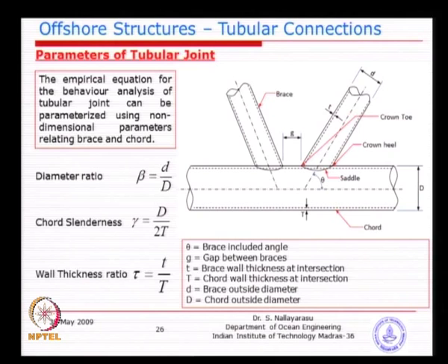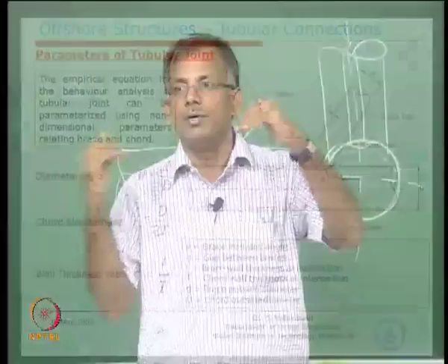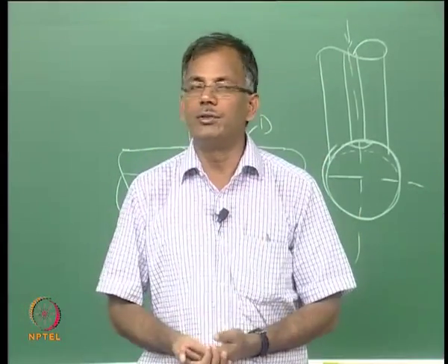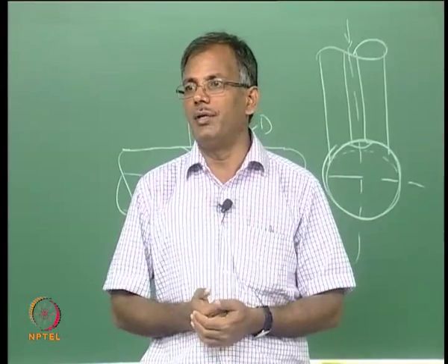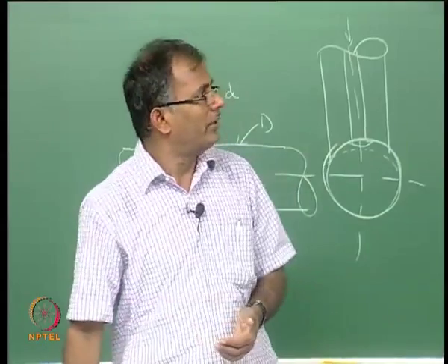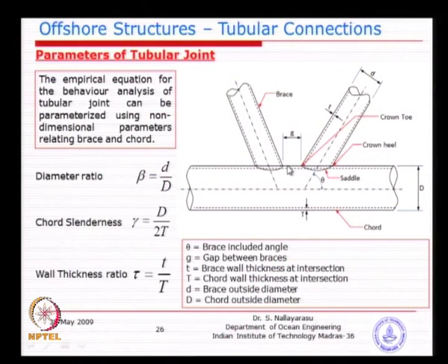So, you need to keep it closer, but as much gap needs to be there because you need to do welding, because when you look at the welding, both welds will overlap. Weld overlap is not very good because of the heat generated during welding 2 times, 3 times. For example, you make this so close that this welding is overlapped onto this welding. Next 2 times you are going to heat, 2 times you are going to degrade the material, and then failure may occur at that location.